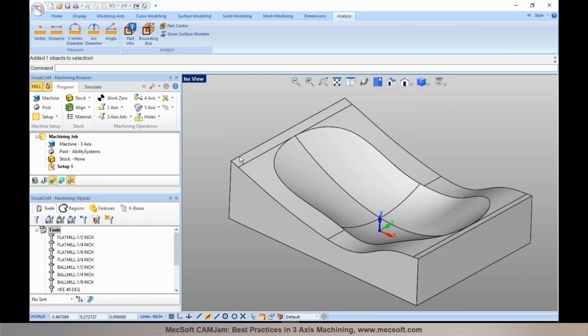Now as far as STEP file format goes, we have AP203 and AP214 file formats, and you could be using either one of the file formats when you translate the files into Visual CAD/CAM. So both file formats should work. You should be able to translate your files fairly well into Visual CAD/CAM. If you're noticing any translation errors or issues, you may want to try one of the other formats. It could be just specific to the geometry. You might be noticing a translation error, so you could use IGES or one of the STEP formats. So I'm going to turn this back to Krish.